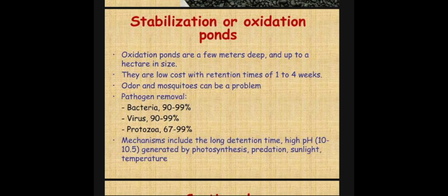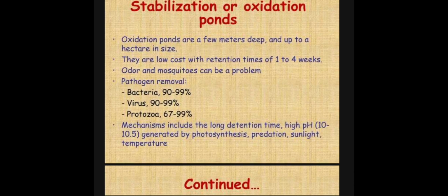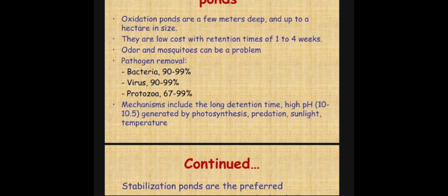The oxidation pond will be exposed to the atmosphere. Due to this exposure, odor and mosquitoes can be a problem. But for pathogen removal, 90 to 99% of bacteria will be removed, 90 to 99% of viruses are also removed, and 67 to 99% of protozoa will be removed.